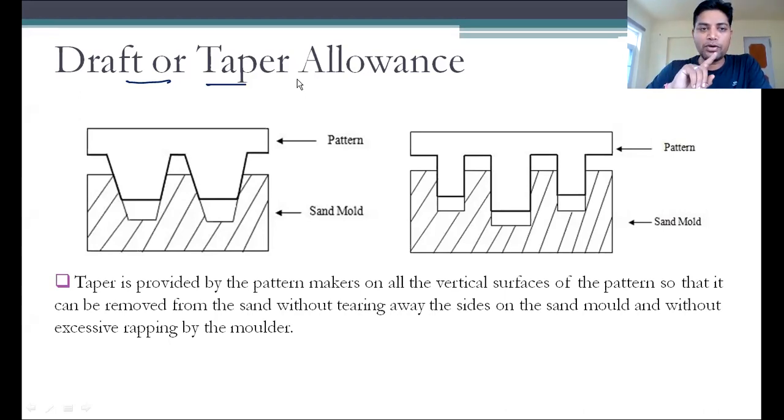You just answer me one question. The material which is coming out from the riser, can it be possible that when it becomes completely solid, it will come out from the riser? When the material becomes completely solid, is there any possibility for it to come out from the riser? No, sir. Then obviously, when this material comes out from the riser, there are two possibilities: the material is in liquid form, or it is in semi-solid form. Only through these two possibilities can the material come out through the riser. If it becomes solid, then definitely it will not come out from the mold cavity.